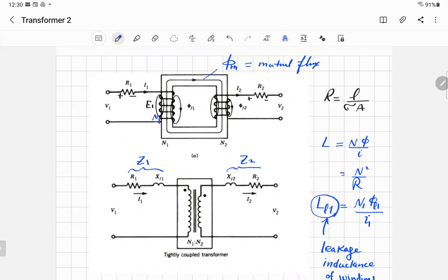And the proof for that: if you have a transformer or adapter and you plug it into the wall, even if you don't connect it to your mobile or to any load, it gets hot. Why does it get hot when I don't load the transformer? Because the magnetic field is built and changing with time, and it intersects with the core itself, producing the eddy current and what we also call the core loss, even if you don't have a load on the adapter or the transformer.